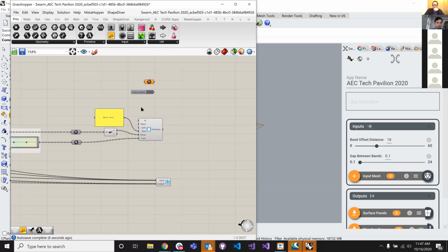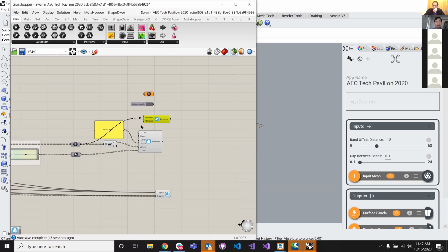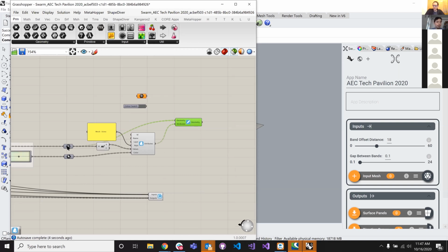create this inject component. So basically what we're doing here is we're taking the geometry that we just computed and we're injecting the attributes into it. And you got to watch out for the trees so that you don't graft things out of control. And I'm going to duplicate